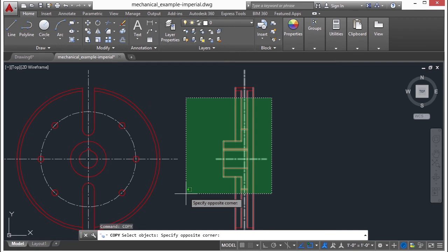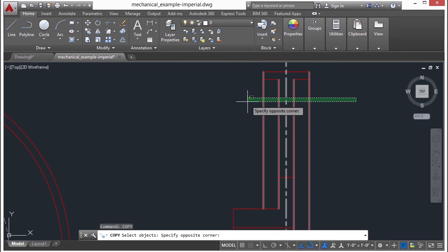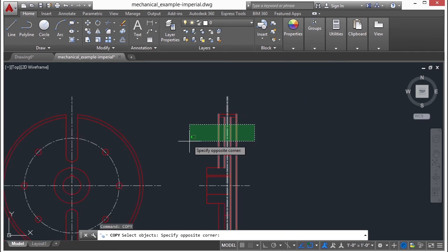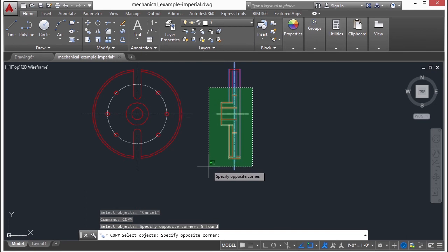You can see the very top part right up there. I'm going to zoom in a little bit. These items there at the top that are still red are not being selected. So they're not highlighted. So if I want to pass through something, I don't have to have this entire line selected inside my window, just part of it. Anything my window here crosses through will be selected. Left click again, and all of those items are picked. See, that's quite simple, very easy.